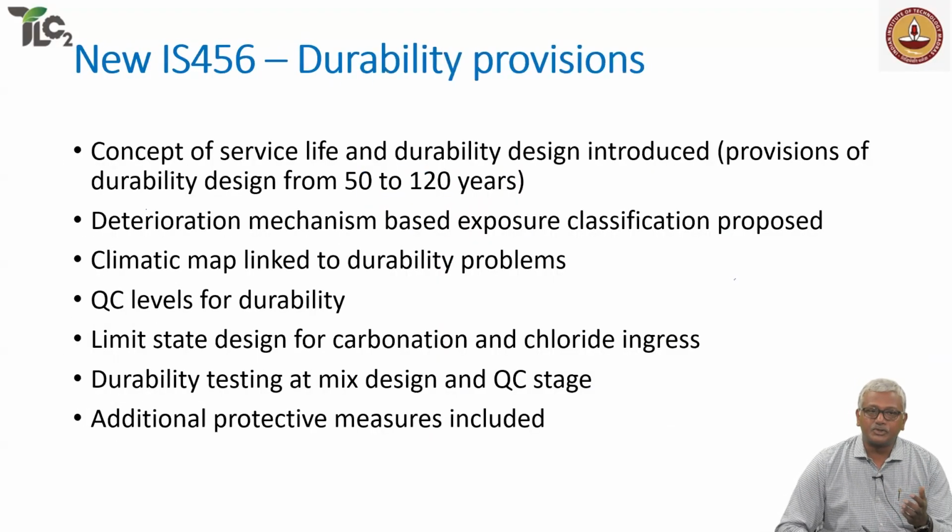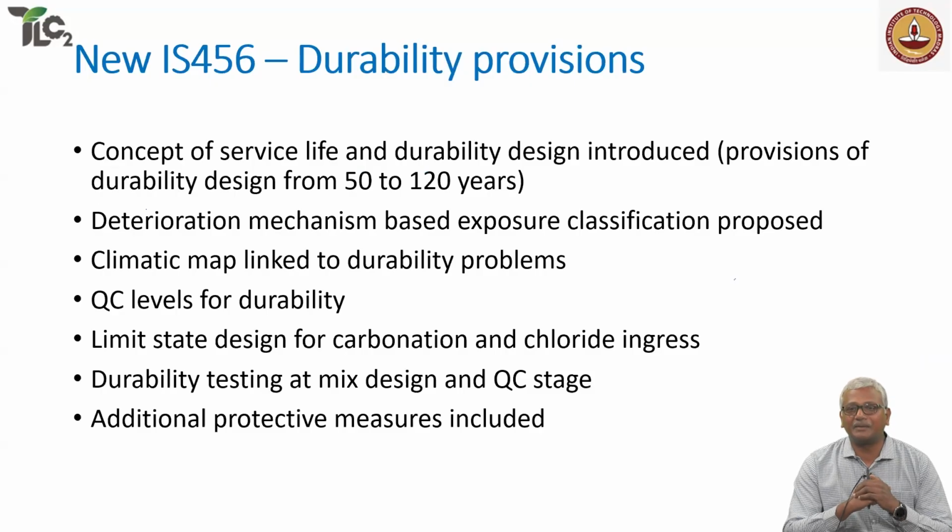Now, we also are moving to a new IS 456 in India. It has been in the works for a long time, but I'm hoping that it will come out within this year. There are attempts now to bring in durability provisions on the lines of what is currently available in the Eurocodes as well as in the fib Model Code. So here a concept of service life and durability design has been introduced, and provisions for durability design for a 50 to 120 year period have been given.